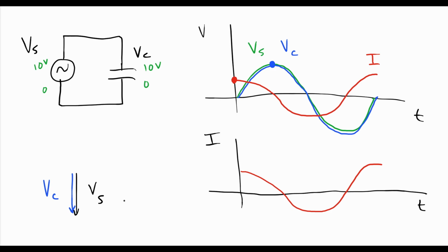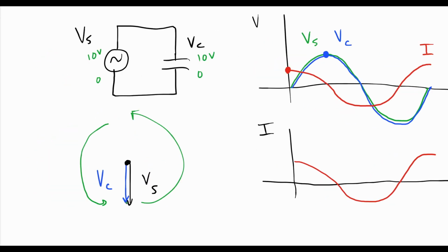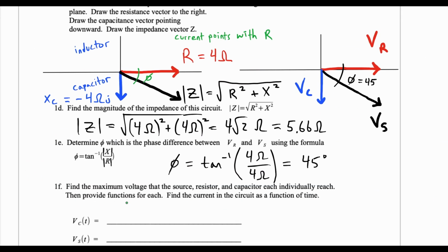They're in phase because the capacitor is the only thing contributing to this, and then of course they would just rotate around together. But what we have here is the resistor voltage is pointed at a different angle than the capacitor voltage. They're 90 degrees apart. And so the source will now have to take both of them into account, is the idea.